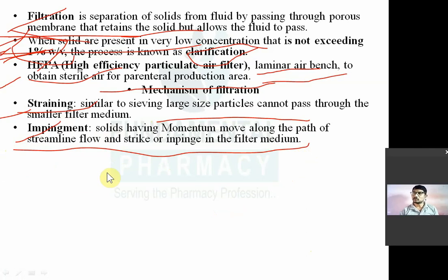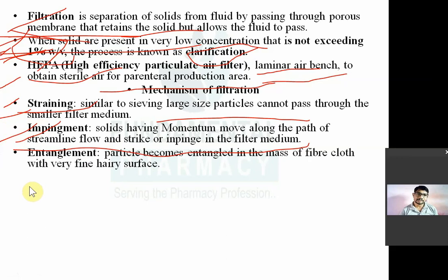So solid having momentum moves along with the path of streamline flow and strikes or impinges with the filter medium. That is another mechanism of filtration, impingement. Okay, remember straining, impingement. Then another mechanism for filtration is entanglement. Entanglement: particles become entangled in a mass of fiber or cloth of very fine or hairy structure.